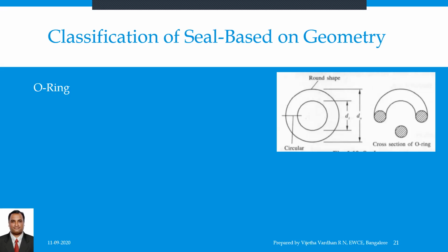The O-ring is compressed in one direction when installed. Application of pressure causes the ring to be compressed at right angles to give a positive seal against the two annular surfaces and one flat surface. O-rings give effective sealing at very high pressures. Primarily, O-rings are used as a static seal because any movement will cause the seal to rotate, causing leakage.